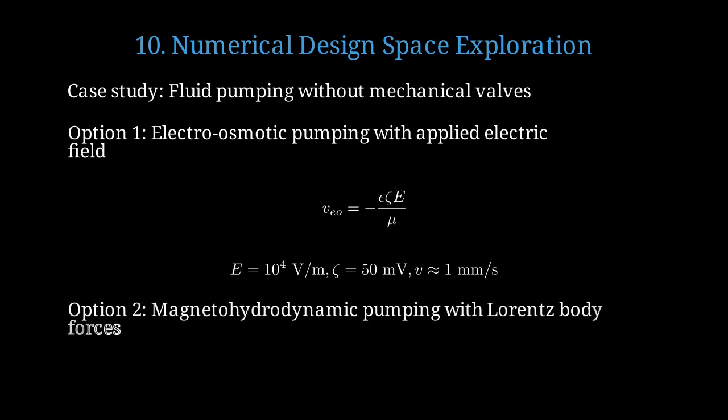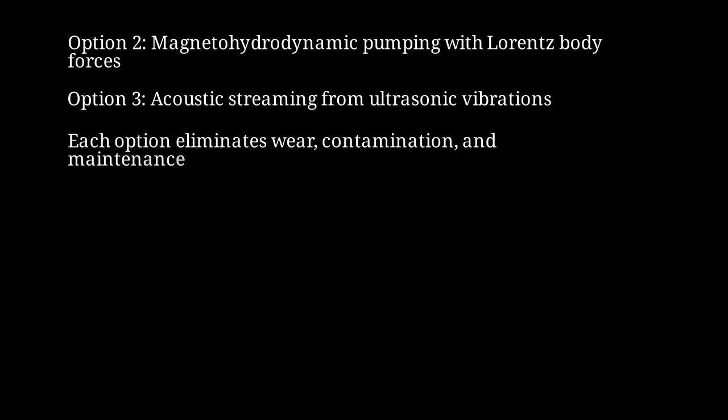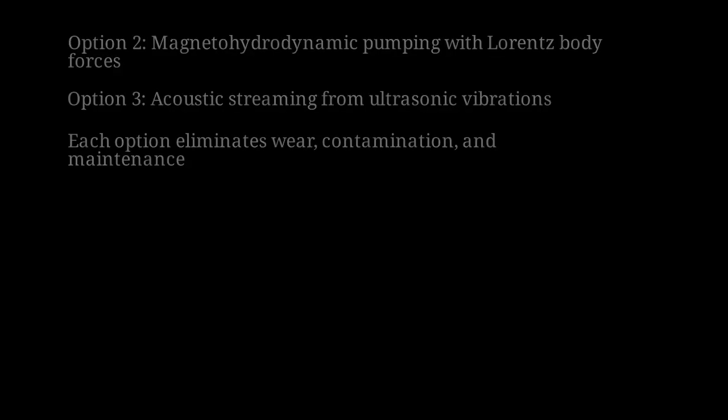MHD pumping uses crossed electric and magnetic fields to generate body forces in conductive fluids. Acoustic streaming induces steady flow from nonlinear effects in oscillating ultrasonic fields. All three alternatives eliminate wear, reduce contamination, and require virtually no maintenance compared to mechanical pumps.